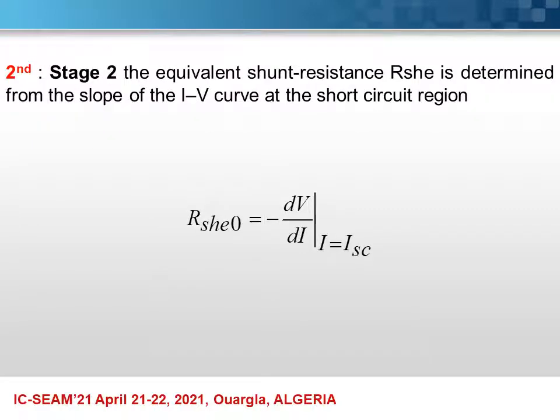Second, we determine the shunt resistance, the parallel resistance, from the slope of the IV curve at the short circuit region, as demonstrated with this mathematical model.